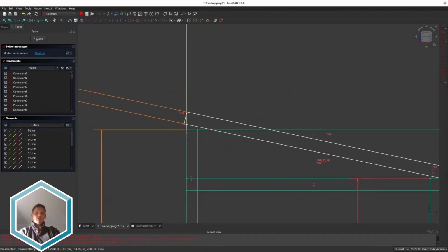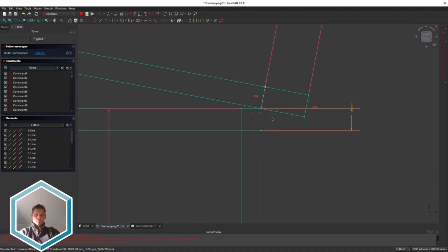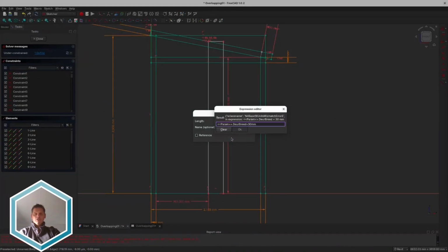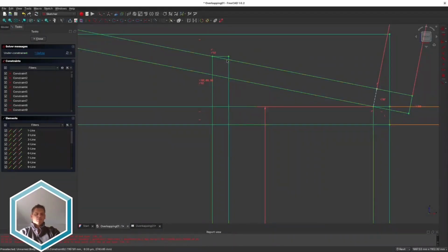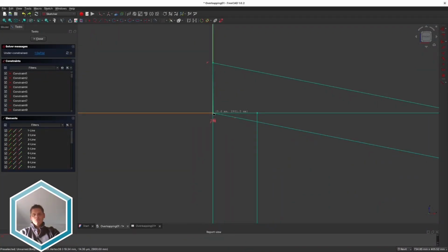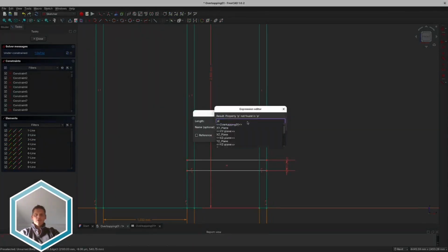And then I'm constraining it and doing a couple of changes here and there. For example, I constrained the top part here, which is a beam, but later on I'll move it downstairs a bit so that I can change the height independently of how tall the entire structure is. I use a lot of formulas which call on values that are in the spreadsheet.